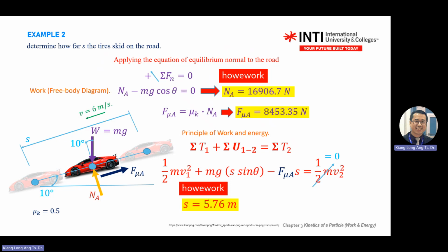Okay, so this is the focus of today. What is the principle of work and energy? There's a work component and a kinetic energy component. What is work? Work is the force multiplied by the distance traveled, and they must go parallel to get positive work. If one of the vectors goes opposite to the other, you get negative work. And then there's an equation for the spring, work done by the spring, and work done by the weight. This one you can read from your free body diagram. I think the spring is an extra one that you need to go and remember. Yeah, so that's it.